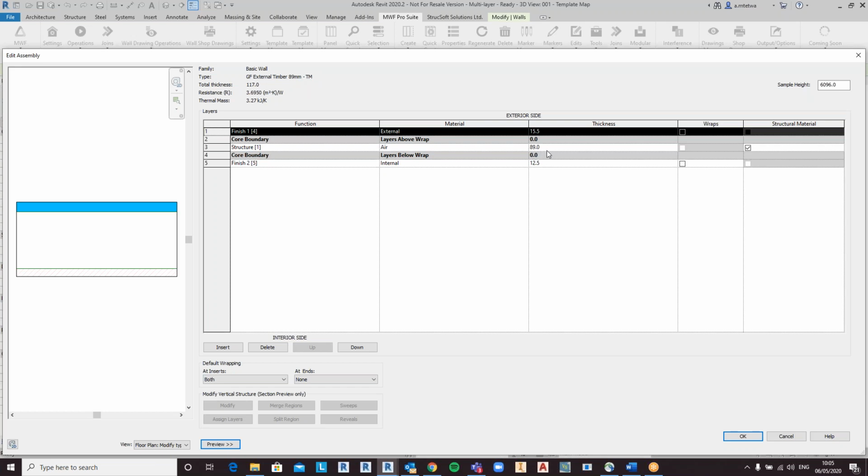Now, this is an important part of where the framing would actually be populated within MWF. It looks for the structural layer, and it would then apply your light gauge framing or your timber framing to this area here. So for applications of the framing, you would initially probably go for the single layer, where you can begin to create, alter the properties, and save it as a template.